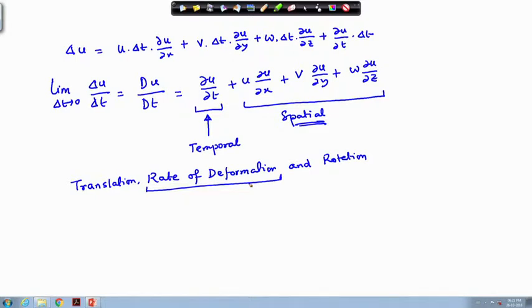So, we essentially need to understand how a fluid element deforms under different conditions, and this depends on the condition of the flow field, or more specifically whether there are relative velocities with respect to the fluid particle we are tracking. Please do not forget, fluid deformation is a Lagrangian concept, and therefore we will focus on only one fluid element. I have come across questions where students ask, sir, you just draw that the fluid element is deforming, and 2 lectures later in control volume it does not deform. So, what is the difference?